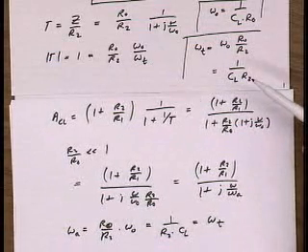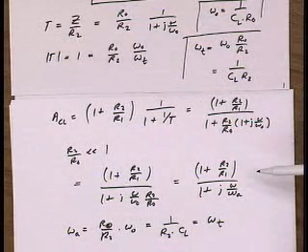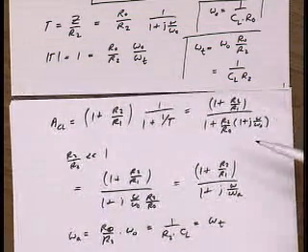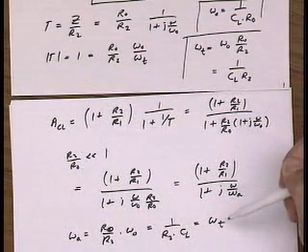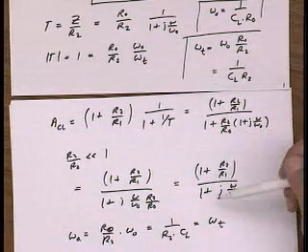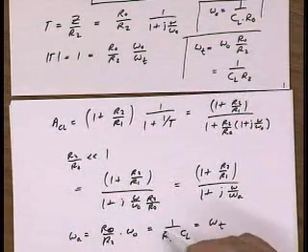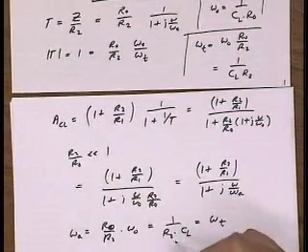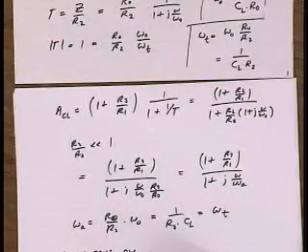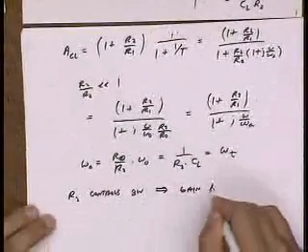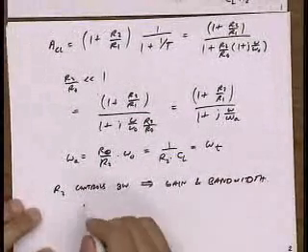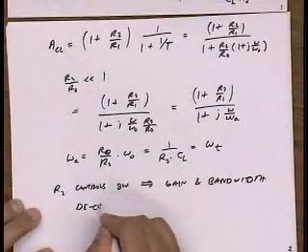Okay, so this shows very clearly that this amplifier has a gain bandwidth product. Let's just say the amplifier has a bandwidth which is always approximately omega t. And because this is only a function of R2, we can see that R2 controls the bandwidth. So that gain and bandwidth are decoupled. I think this is the important point, that the gain and bandwidth are decoupled.